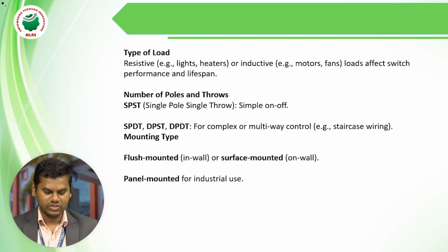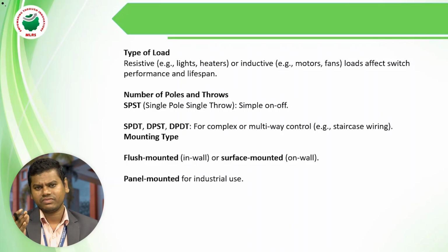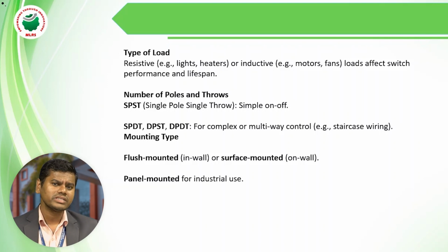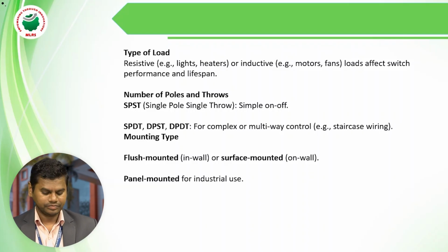Next, type of load. Let us assume first of all there are 3 loads: resistive load, inductive load, and capacitive load. Here, resistive loads are things like heaters, and inductive loads are, for example, motors and fans. Loads affect switch performance and its lifespan.